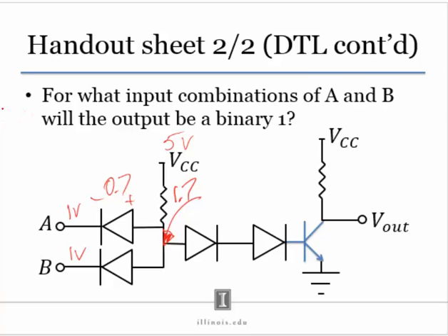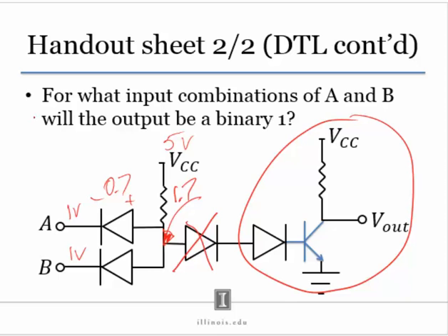Notice that if we didn't have this diode here, then 1.7 volts would have been enough to turn on the inverter, right? And we would actually have the output of 0, which is what we don't want, okay? The high zeros could result into a confusing output there, okay? So this diode there in the center is just to increase the threshold a little bit, right?